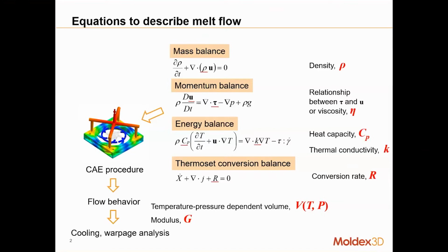and so on, this will make your simulations much more accurate, since your simulations run based on the governing equations. And these governing equations require material properties in order to solve for the field variables. For example, when we look at the mass balance, this requires the density of the material. And when we look at the momentum balance, there are also the viscosity terms. And the energy balance will involve the heat capacity and also the thermal conductivities.